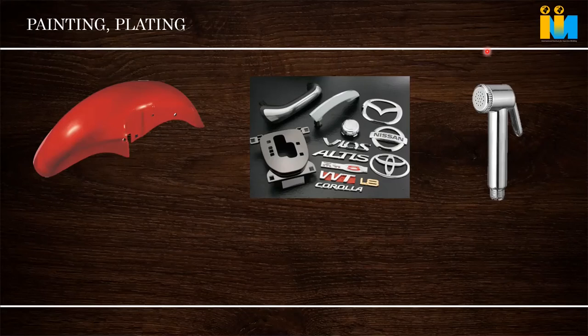Whenever I attended issues in automotive, they were very critical, because normal parts look very good. After painting, some marks and line marks show up, because the problem is in the molding. Then we have to attend to the gate size, like I told, proper filling and proper holding. If you give excess holding, stress will be built up. After painting, after some time that area cracks because stress has built up.